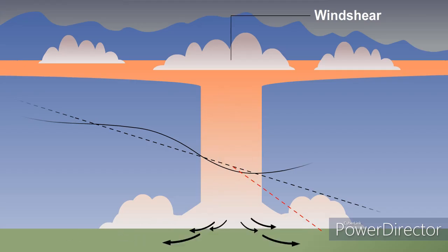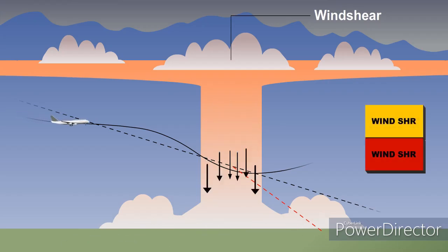Mode 7, which has priority over all other modes, provides the crew with visual and oral alerts and warnings when entering a potential wind shear area. To achieve this, it requires inputs from ground speed, airspeed, barometric height, rate of descent, and radio altitude. The system reacts to the onset of wind shear conditions. This allows crews to initiate the escape maneuvers earlier, giving them a greater chance of avoiding a potential accident.